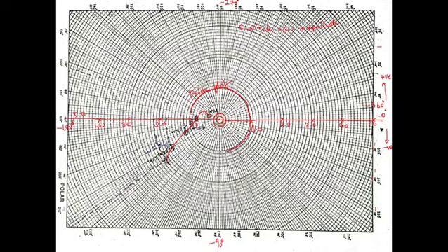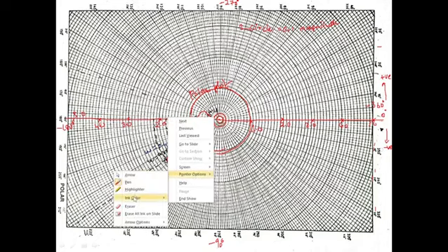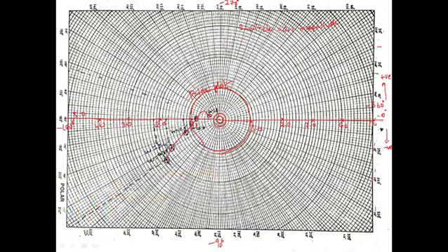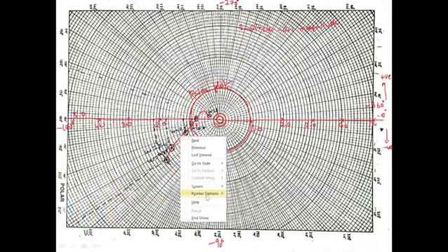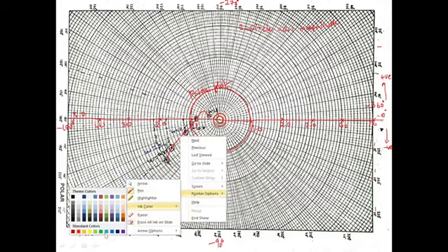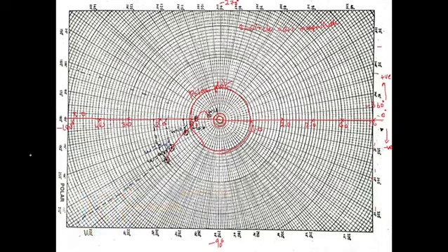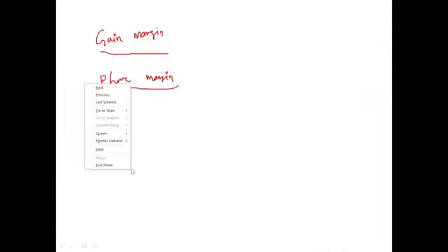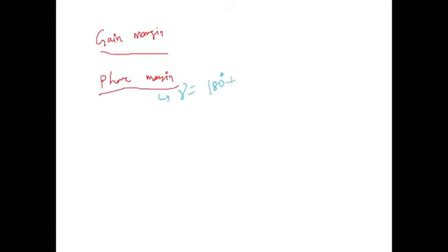Now you can see that this is the unit circle, right? The value could be 1, right? Both the unit circle and this polar plot intersect at one point, right? So this is the point. Can I trace that point outwards like this? This is the point where these two curves meet, right? Now we have to mark that point. That is nothing but phi gc, right? That phi gc you have to add to 180 degrees. If you want to find the phase margin gamma, you have to add 180 degrees plus phi gc.